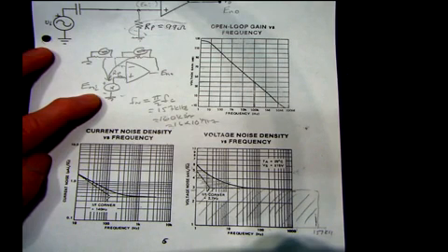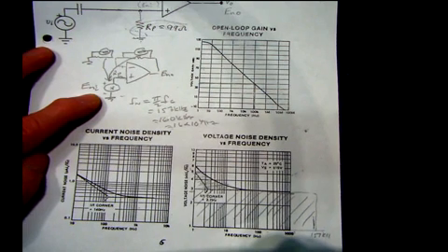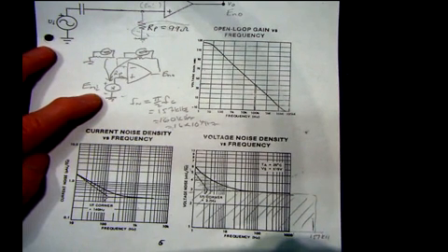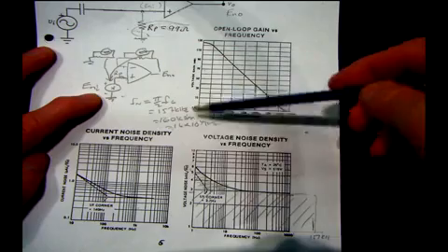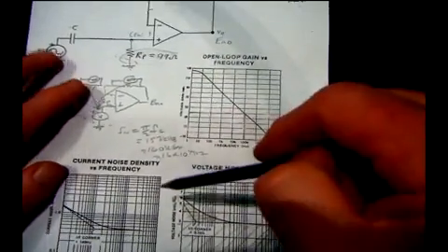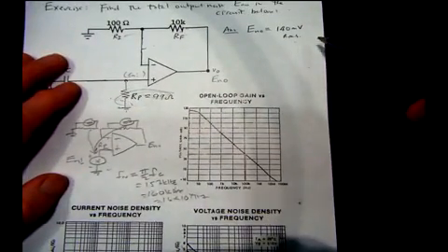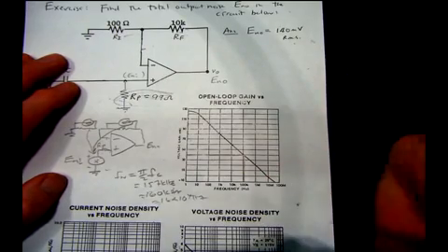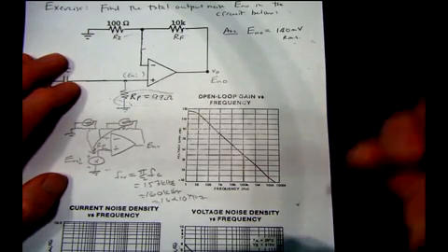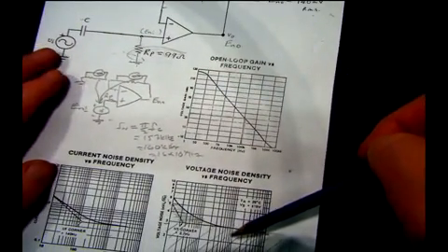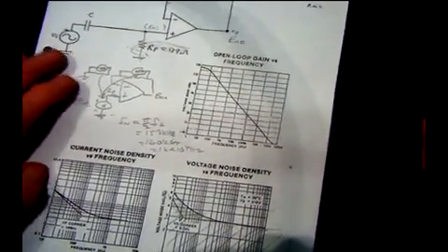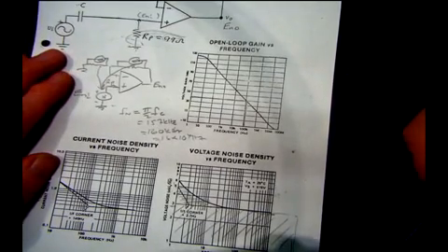I guess that accounts for 120 millivolts of the noise then, because when we amplify it by 100, that'll be roughly ballpark. The major part of the noise would be due to this voltage noise. Does that make any sense to you at all? This is using rough approximations.